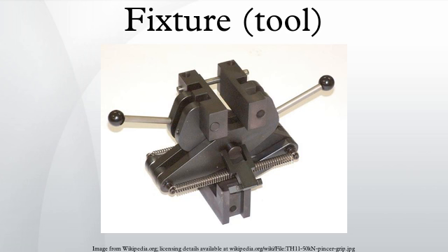Design: fixtures must always be designed with economics in mind. The purpose of these devices is to reduce costs, and so they must be designed in such a way that the cost reduction outweighs the cost of implementing the fixture. It is usually better, from an economic standpoint, for a fixture to result in a small cost reduction for a process in constant use, than for a large cost reduction for a process used only occasionally.